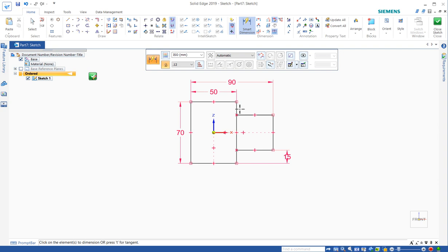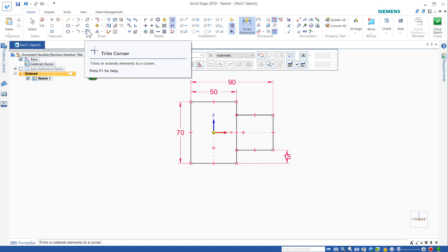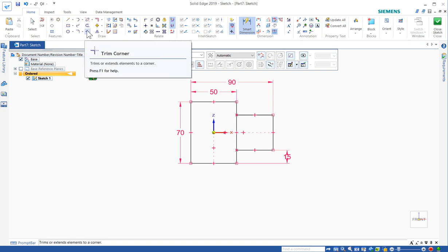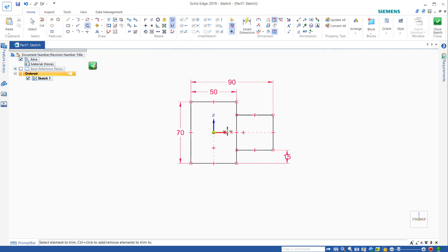And then we have one extra little element in here, and then we can go ahead and trim that. So you have a trim and extend. We might talk about this a little bit more. The trim tool removes elements. The extend joins elements that have gaps.